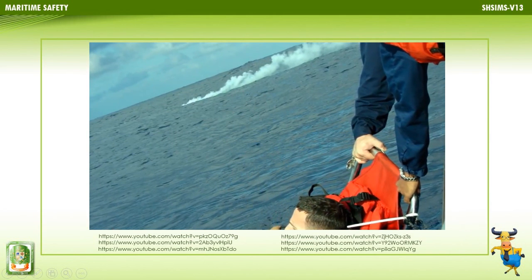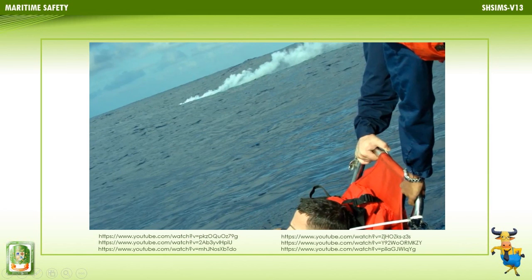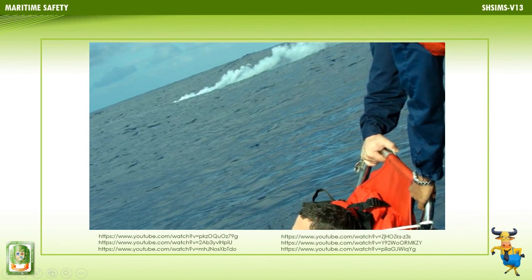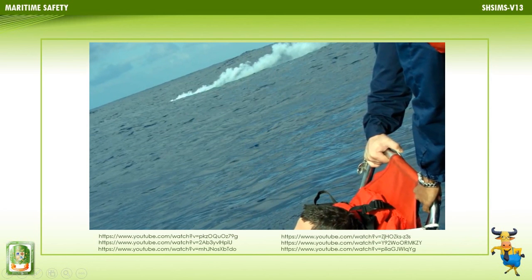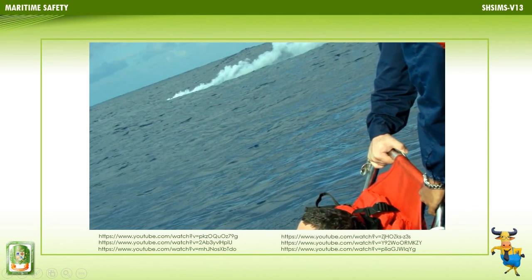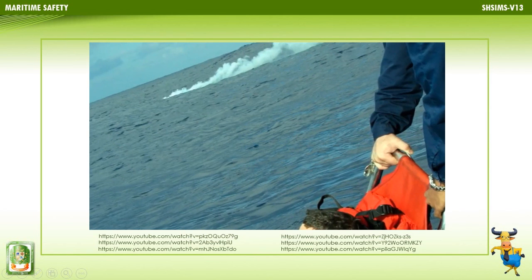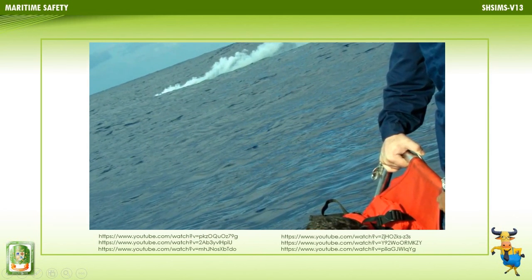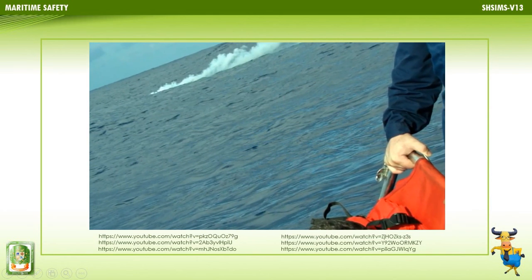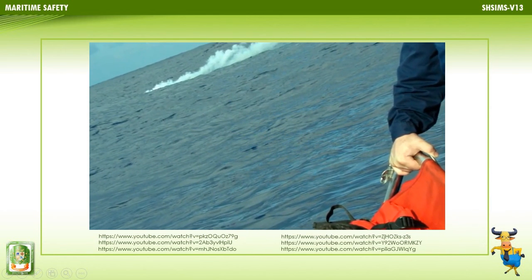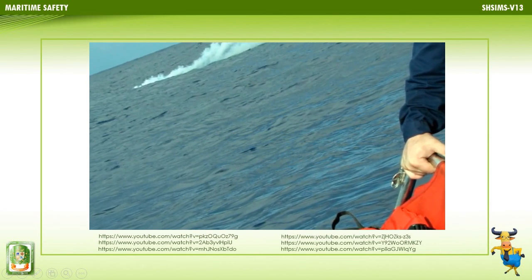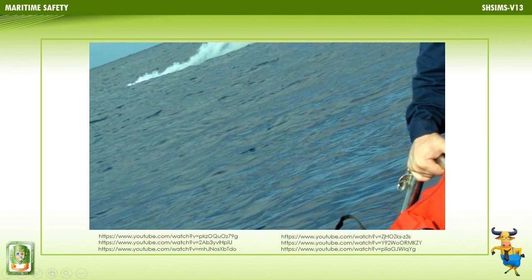The average CRV carries 4 crew as its normal complement, and in the event of a man overboard there will be 2 crew needed to help in the recovery of the man overboard, and 1 on the helm. While turning around, sighting the man overboard, then preparing to approach and recover, sending a distress call may be an unwarranted distraction. In the event of an unwitnessed man overboard, or where the CRV fails to locate the man overboard, then a distress call must be made.